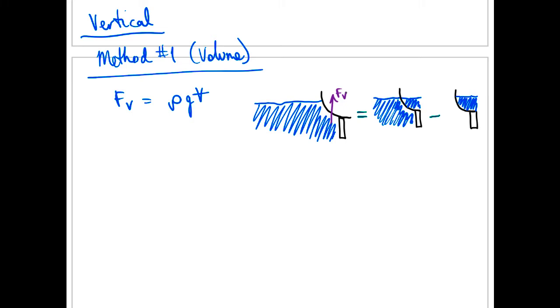So in the next picture I've shown here, we imagine that there's fluid filling the space above the gate and below the gate. And I'll label this as a no force situation. Because we could imagine if now you're looking at the forces on that gate in the vertical direction, the forces that are above the gate and below the gate would actually balance. And so in this type of situation, we would expect there to be no actual net fluid forces pushing on the gate. So we'll call that the no force. And then in the picture on the right there, we have the case where there was just fluid filling the space above our circular gate there. And in that case, now we know how to calculate that one. We would expect the vertical force downwards like this.